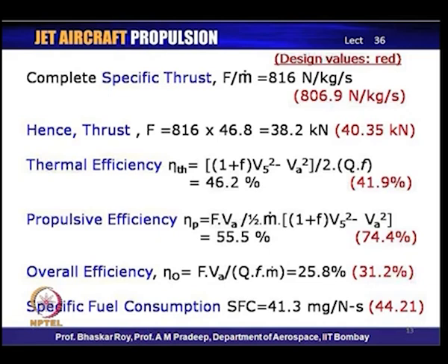So, we have an off design operating condition now, where certain parameters are indeed higher than the design point parameters, in terms of compression ratio and specific thrust. However, the mass flow is lower, and the thrust produced is lower. Indeed, it is supposed to be flying at a lower Mach number.